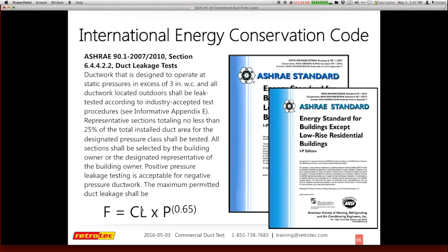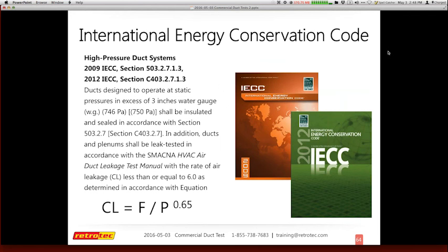Even if you can't achieve it, you go to your gauge in Settings and set the default test pressure to 4 inches if you're testing at 4 inches, 8 inches if you're testing at 8 inches. Whenever you take a reading and press the at key, you'll always get results at the test pressure you want, no matter what the actual pressure is.